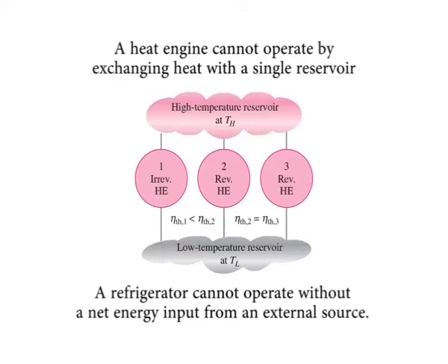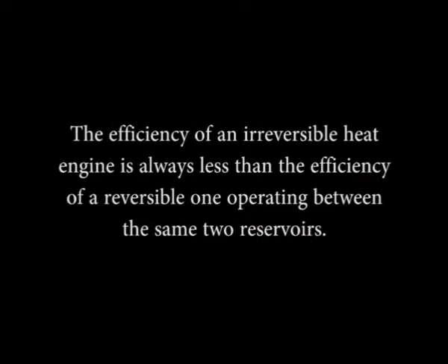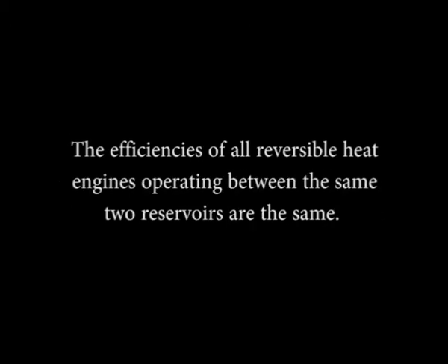2 conclusions pertain to the thermal efficiency of reversible and irreversible, that is actual, heat engines, and they are known as the Carnot principles, expressed as: the efficiency of an irreversible heat engine is always less than the efficiency of a reversible one operating between the same 2 reservoirs. The efficiencies of all reversible heat engines operating between the same 2 reservoirs are the same.